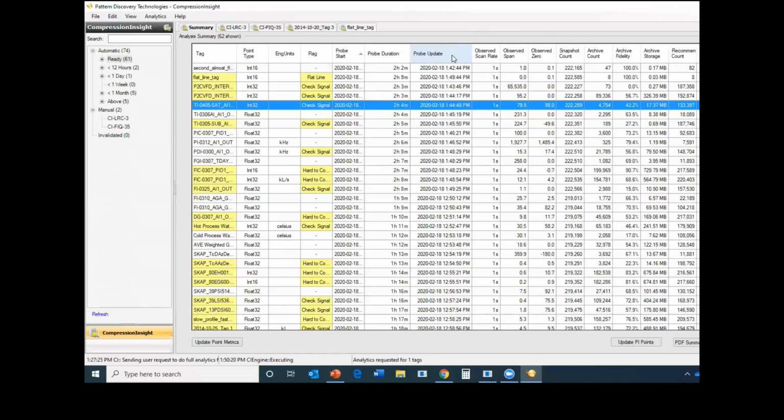Gotcha. We could do exactly what you're saying for any data historian by simply, whatever means they set exception to 0 in those data historians, we will get those raw snapshot values. There is no question.